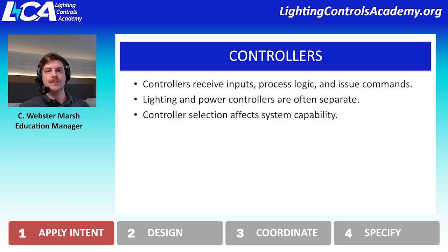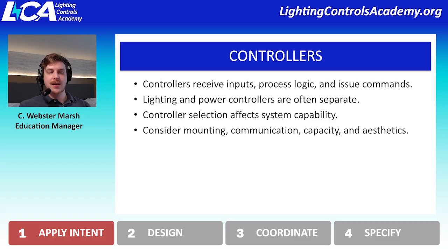Some systems don't have the same capabilities, such as advanced capabilities like conditional logic. So make sure that your sequence of operations is thoroughly vetted, and then you can reach out to a sales rep or some other group that might be able to help you verify that the system you're planning to select does align with your sequence of operations. That's very helpful to making sure that the system will be completed to your specifications.